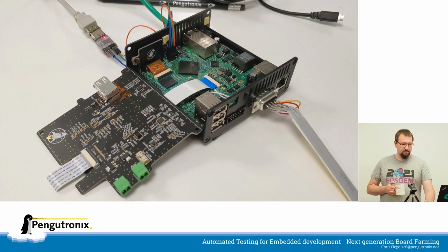How does it look like in reality? Well, we already have got some prototypes on our desk. So this is our test automation controller. The bottom board, the lower board, this one here is the board with the CPU. It's an Octavo Systems SiP here. And the Ethernet switch is integrated here and everything we need for the device under test connections. Those are mostly on the front-facing side of the housing here. And the other board is the power switch. That's mostly empty PCB. It's just everything you need to switch power on and off.